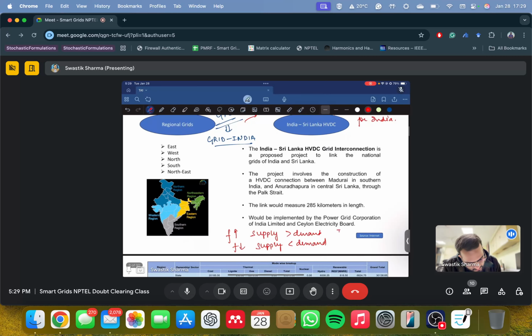And this operating range, according to the Indian Electricity Grid Code IEGC 2023, I hope it's 2023, yeah, it's 49.9 to 50.05. Right. So within this operating range, it has to manage.